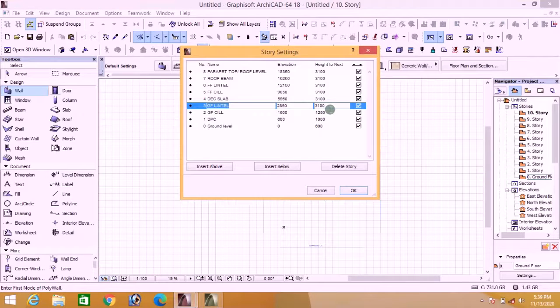Now, when you have 750, then you are going to create your decking beam. Decking beam of, let's say, 250, then 250 with the deck slab. You add them up together. You do your mathematical arrangement here. Thickness of the slab is 150. The decking beam is 250. 150 plus 250 gives you 400. Is that understood? 150 plus 250 gives you 400. Now, this 400 will be sitting on top of your 750. So 400 plus 750 will give you 1150. So we'll have 1150 on top of our lintel to bring us to the decking top.